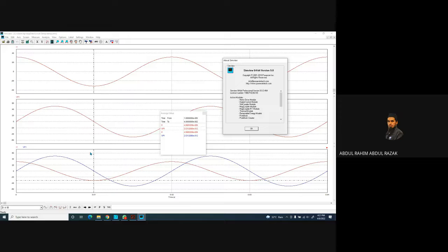So you don't have the X1, X2. You have to take note of that. Maybe you have to download again, or you can use this one directly. It doesn't matter, but you have to take note that when you simulate, the reading will take place on your entire screen. If you are generating a frame from 0 seconds to 0.04 seconds, that's the reading of your result: average value, RMS value.